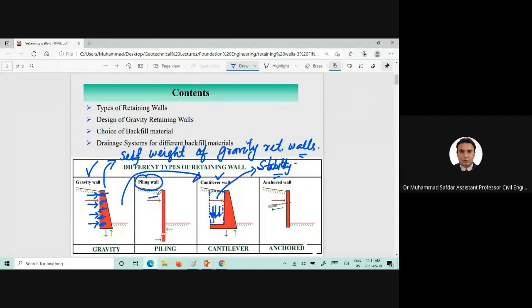Now these sheet pile walls are thin sheets, and they are unable to retain a significant amount of lateral earth pressure. Therefore anchors, tiebacks or braces are provided just to give extra strength to the sheet pile walls.